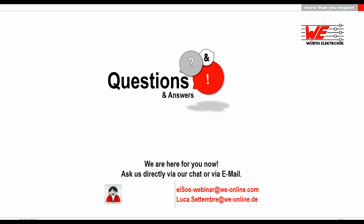Can I change the GNSS constellation used by the module? Thank you for the question. Yes, this is possible. In multi-GNSS modules, that means in all our solutions, you can switch between the systems. For example, in the ELARA line, you can switch between GPS GLONASS and GPS only. In the Erinome line, where you also have Galileo and Baidu, you can set the other combinations.